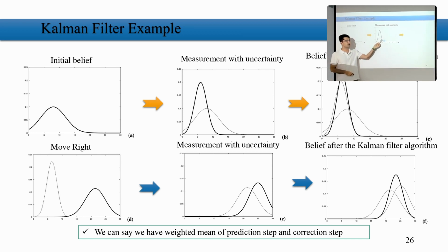So robot measures the environment, uses any kind of sensor that it has, measures the features from environment, and that measurement says, okay, robot is like over here, not there. Measurement says this. So what does Kalman filter do? Based on the calculation of Kalman gain, and based on the certainty of each one of these, that is now very clear, it updates the belief of where the robot is. How is that happening? It is happening like this over here. The belief is changing based on this new black curve, Gaussian distribution. Then we are updating where we are believing that the robot is.